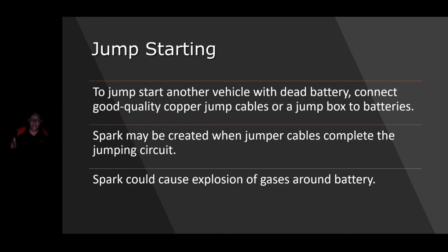You know the rules when it comes to jump starting a battery. On the dead car, the car that you are jump starting, you never put the negative jumper cable on the battery post with the positive on there, right? You put the negative off to the engine somewhere or to the body of the car somewhere so that you do not get a spark near the battery. Getting sparks near the battery causes explosions, and that's not good, okay?